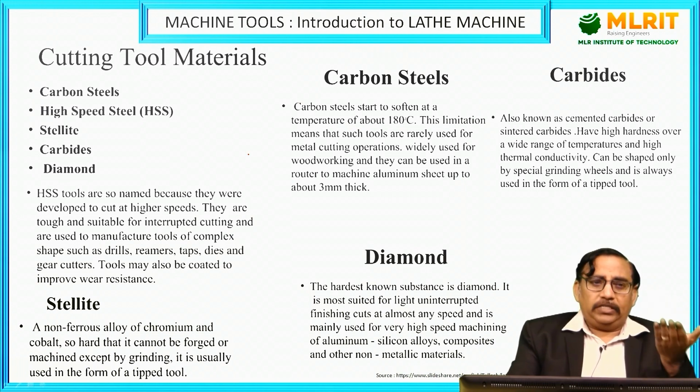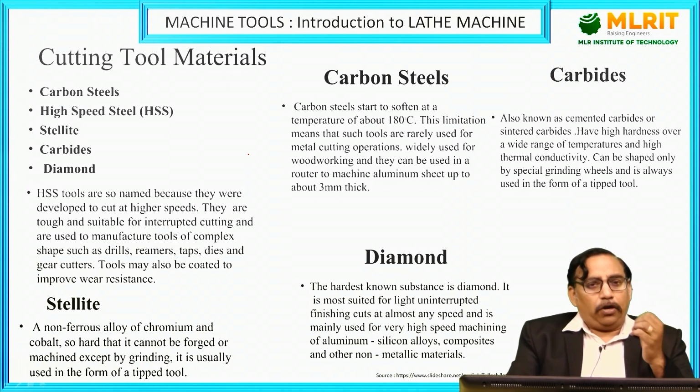Coming to stellite, it is a non-ferrous alloy of chromium as well as cobalt, so it is hard, and it cannot be forged, and it cannot be machined except by grinding. It is usually used for tip tools, general tip tools.